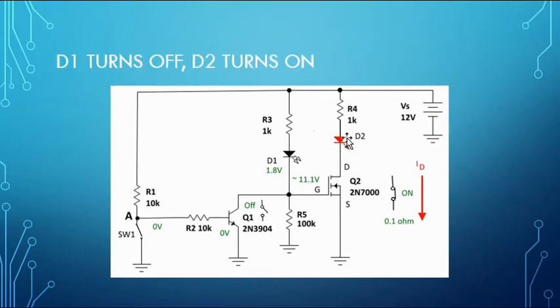The result is this switch is open, so we're going to have current flowing through here. This one, if we look at the path, it goes through a 1K to a 1.8K to a 100K. 100K is not going to give enough current to light this LED. There will be current flowing through, but it'll be so dim we probably won't see it.